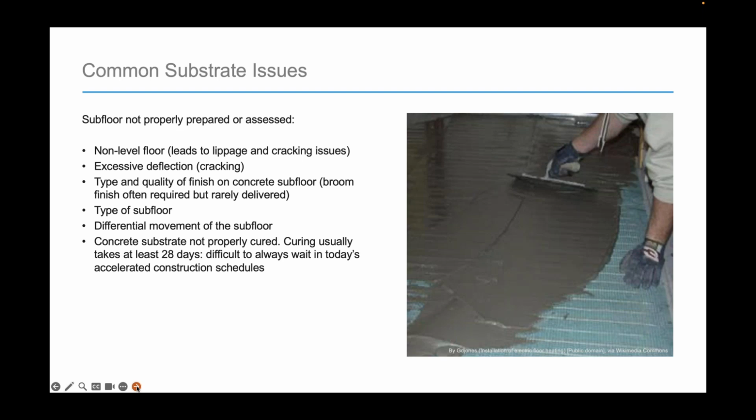Subfloor not properly prepared or assessed. A non-level floor can lead to lippage and cracking issues. Excessive deflection can lead to cracking. The type and quality of finish on a concrete subfloor; a broom finish is what we require. The type of subfloor, differential movement of the subfloor, and the concrete substrate not properly cured. Curing usually takes about 28 days, and everybody's in a hurry, so it's difficult to wait.